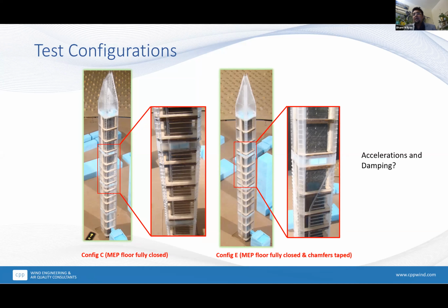And one of the things we have to remember is that in buildings, there's a separate topic called damping. And interestingly, when you're talking about really high-rise towers, there's something called accelerations. Let's assume you are at the top of a very high-rise tower, in a penthouse, living there. If the building has a very high acceleration, whether you're a tenant or you own that place, you would feel the building is actually moving. It's about perceptibility, and it varies from person to person. There's still a lot of research ongoing on that. We could talk for hours about accelerations and damping in buildings.